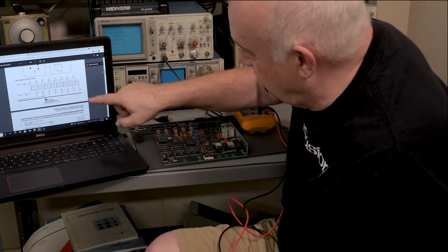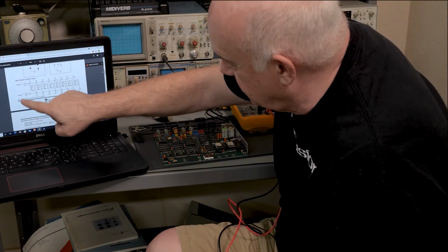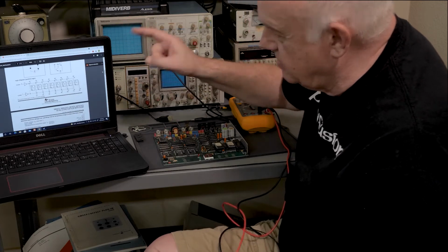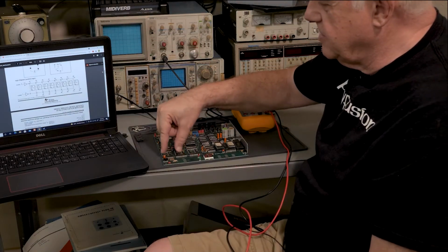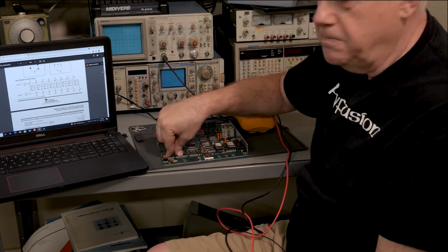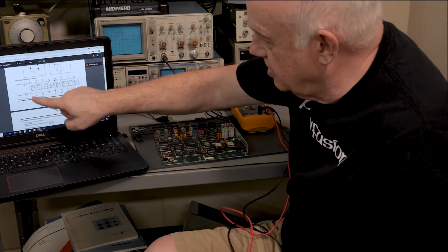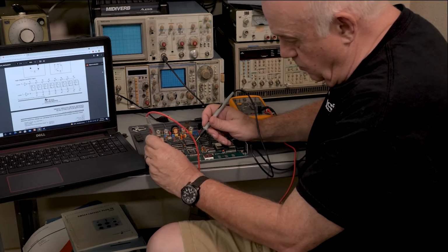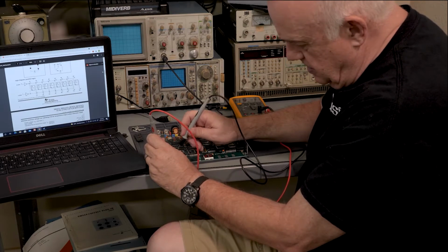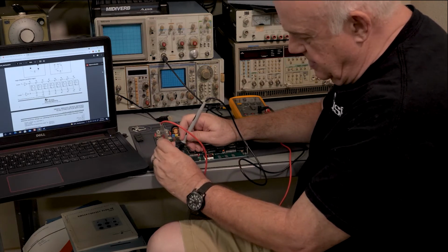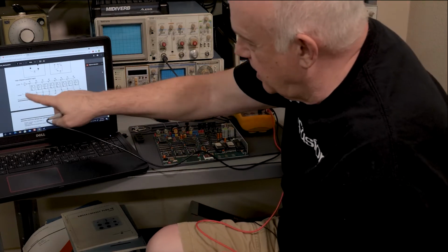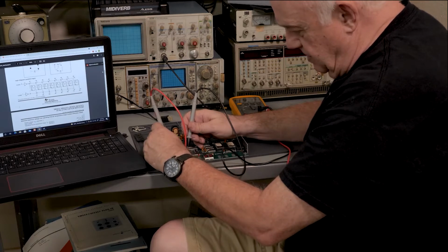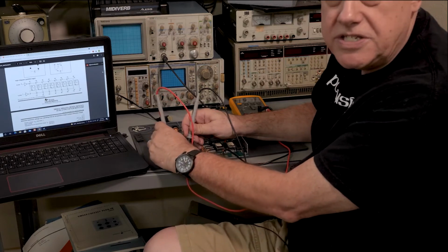Now let's try to figure out where this clear and clock go. All right. So I'm going to make another guess that these 2 together make a 16-bit pair, which means the clock and clear should be tied together. Let's see if that's true. Does pin 1 go to pin 1? Yes, it does. All right. So they are tied together. Are the clocks tied together? Does pin 11 go to pin 11? Yes, pin 11 does go to pin 11.